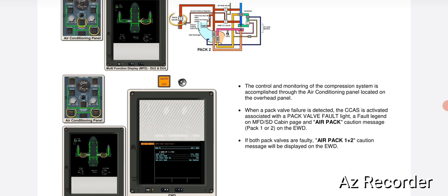Remember, this is only the right pack valve where hotel mode will be running. It opens if all conditions are met, like no leak from the LH engine bleed check valve. Then the bleed selected on valve is open. If only the bleed selected valve is open, the pack valve of the RH side will open.